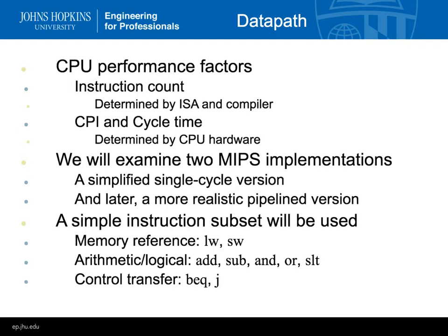In the next 3 units, we're going to talk about actually 3 implementations of the MIPS. We're going to start this week with the single cycle version, where the instruction is read and interpreted, and hardware is used to cause the computer to do the action that the instruction wants, and it's going to all happen in one cycle. We're going to talk about multi-cycle next week.